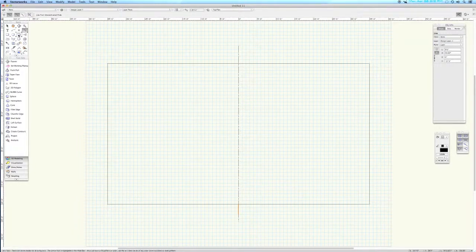The arc is this tool here, and you can see that its keyboard shortcut is the 3 key. The other thing that we need to know is that for every tool up here we have modifiers. I can click on any one of them to select them. The other thing I can do is the keyboard shortcut is the U key, and the U key will just cycle through each of the modifier keys. The modifier that I want to use is the second one, which is 3-point mode.